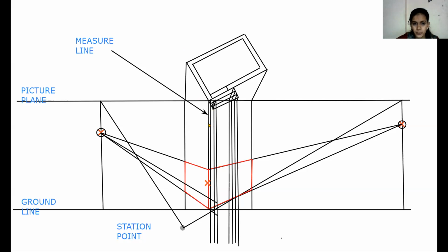Consider the 2nd point vertical line. This point's vertical line is this line. So join the left vanishing point to this 3rd point and extend it up to that 2nd vertical line, like this. And for the above 4th point, we have already connected it with the left vanishing point, but you need to extend it up to this 2nd line. So it will be like this.